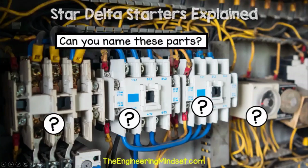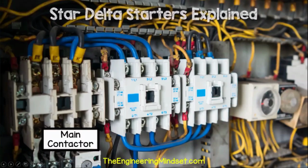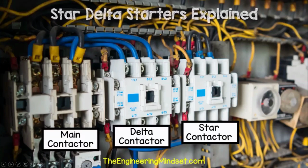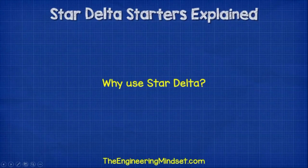So coming back to this real-world photo of a star delta starter, can you tell me which part is which? 3, 2, 1. Correct. This is the main contactor, this is the delta contactor, this is the star contactor, and this is the timer. Notice on the star contactor, they've just connected 2 wires into the same terminal to create that star point. So why then do we use star delta starters?